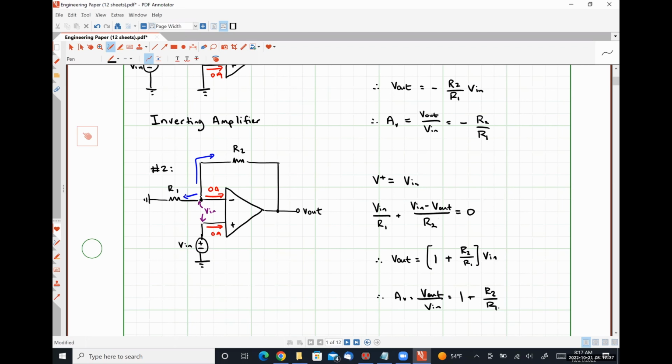Effectively, what a unity gain buffer does is it allows you to use a sensor that is only capable of generating a small amount of power and replicates that signal at the output, but allows the power supply to provide any necessary current that is needed further down the line, so that you're not relying on your sensor to generate the current to drive your system and all that kind of stuff. So critical component in a lot of instrumentation and control systems, right?